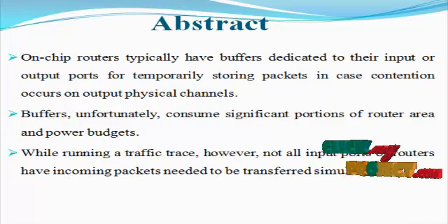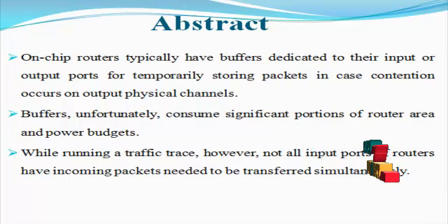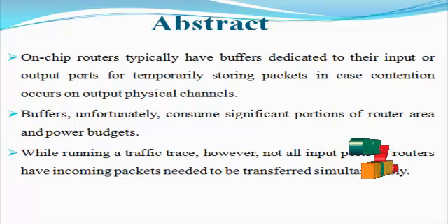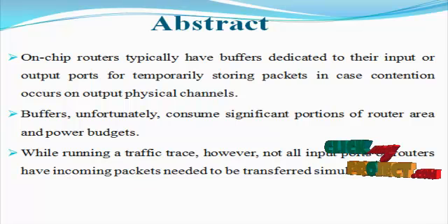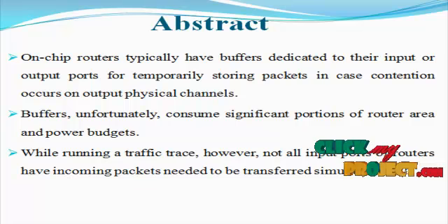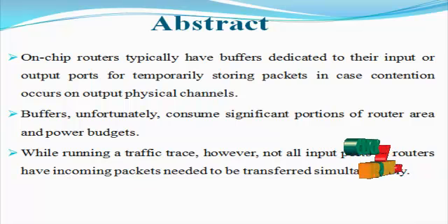In the multi-core system, processors communicate together through a 2D mesh network of routers. A network interface is located between the processor and its router for transforming the processing message into packets to be transferred, for the overall architecture design. In a typical router, each input port has an input buffer for temporarily storing the packets. In case the output channel is busy, the buffer can be a single queue, as in the full router, or multiple queues.